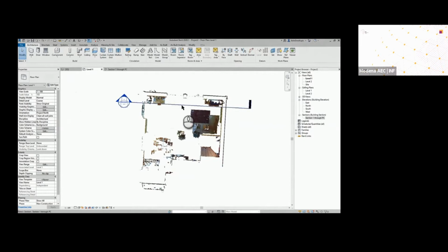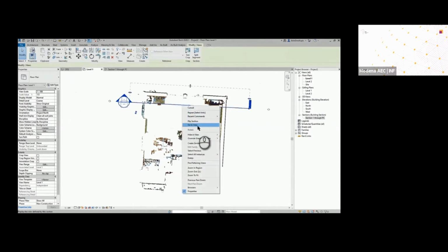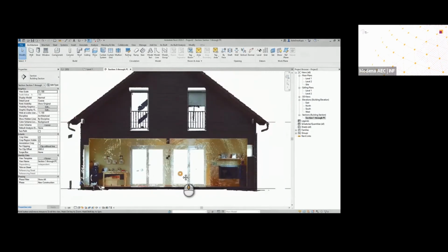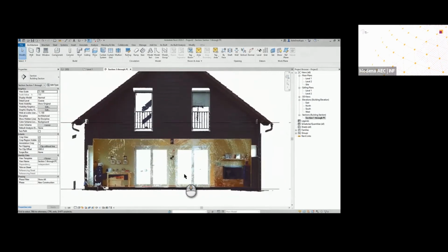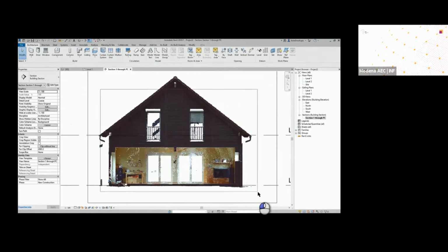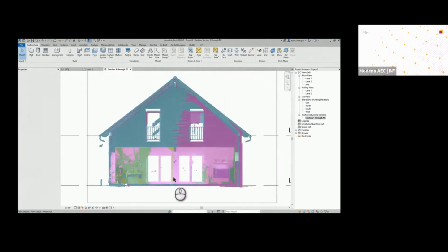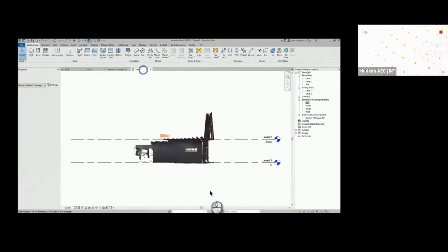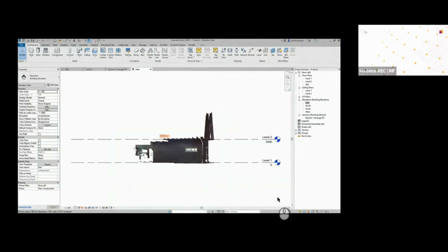And of course, utilizing section tools, you can actually go see how these sections are built up within Revit. Because we already have scanned for this data, Revit is simply utilizing different views in order to help you find and identify key spots. As you can see, I've done a pure section through this house. I can see what's happening inside, and of course, what's happening on the top. Remember, Revit pulls all this information because we are utilizing levels, sections, floor plans, and 3D views.